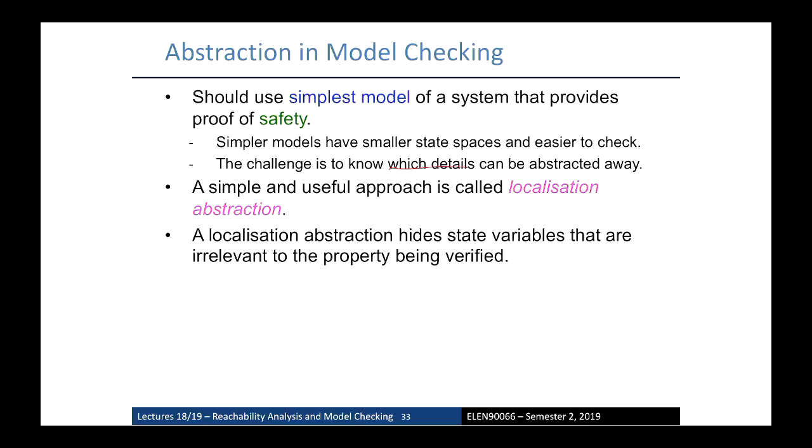It also doesn't work because typically when you abstract stuff, you end up with non-deterministic machines. Remember, when you've got an FSM and you are stripping info out of it, the guards become simpler because you're taking information about the transitions away. Typically, you will end up with a machine, maybe it's a one-state machine, if you abstract all of it out and it's just got a whole bunch of self-loops on it that are all non-deterministic. Okay, maybe that's too much abstraction.